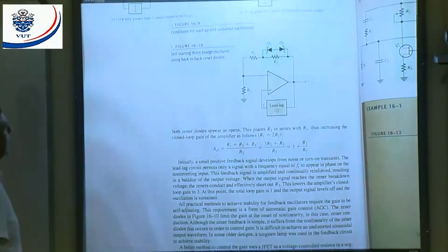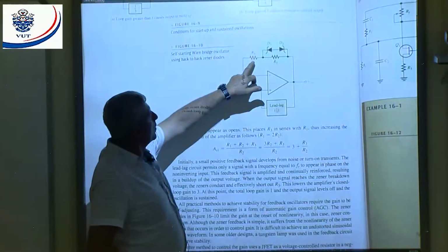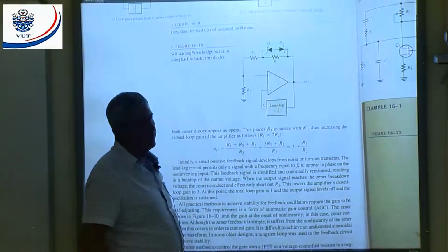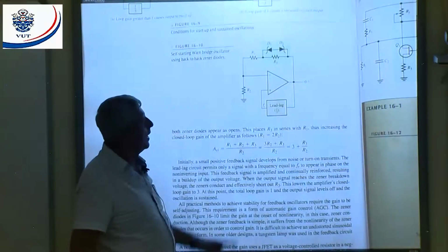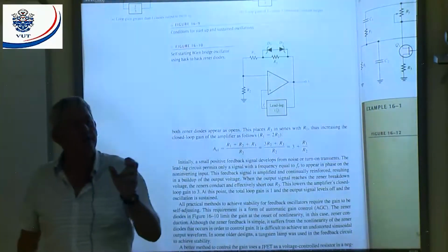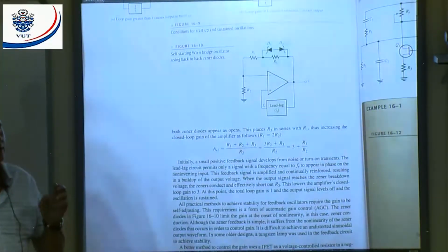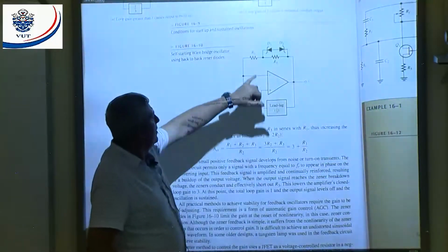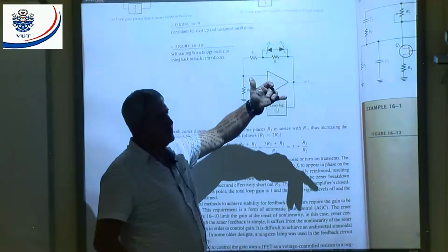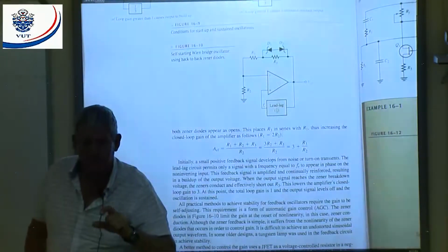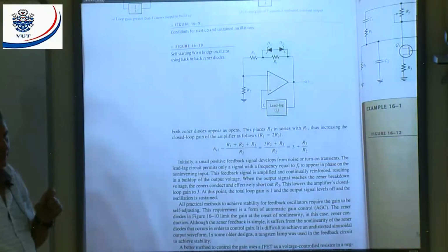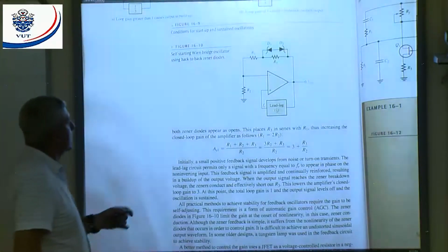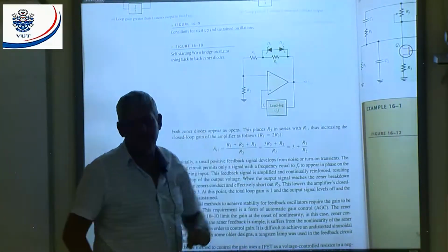That means what will determine my gain? My gain will be determined by R1 plus R3 divided by R2 plus 1, all right. You with me? That will determine my gain. That means now I will have a gain larger than 1, and it will start oscillating. When it starts oscillating and the voltage goes over a certain value, the Zener diode voltage plus 0.7, what will happen? It will start conducting, all right. That means the one Zener diode will be reverse biased, the other one will be forward biased. Doing what? Basically short out R3, all right.